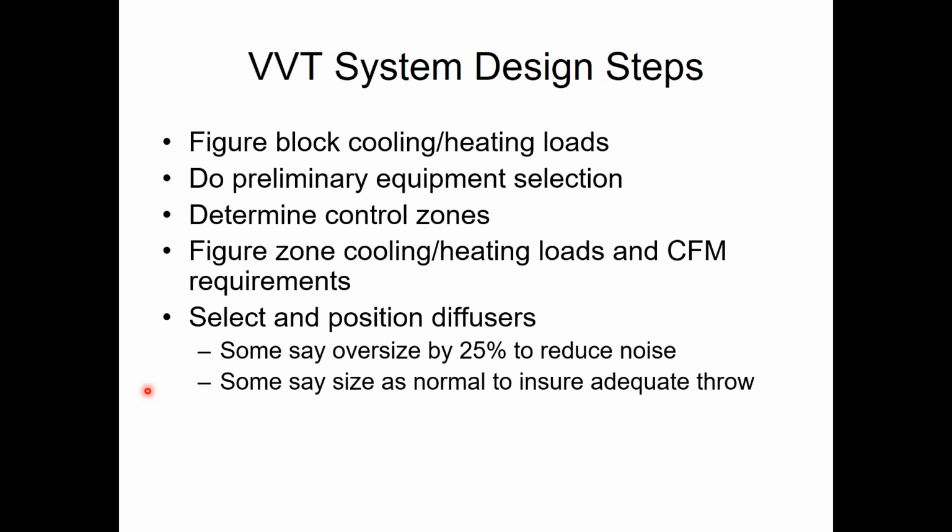Some people will tell you that you should be oversizing the diffusers to reduce noise. I'm not a fan of that. For VVT purposes, if you normally round up on all your sizes anyway for diffusers for all of your jobs, and you're having good luck with that, that's fine to do on VVT as well. But don't do it because it's VVT. There's no reason to upsize because you think the VVT is going to be a problem.